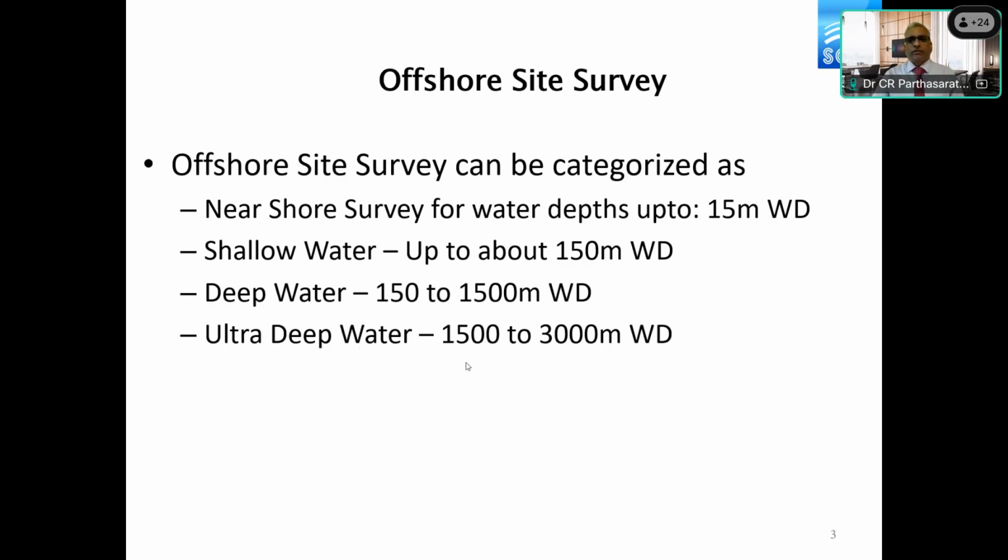The offshore site survey is the first step in the assessment of any offshore structure, to have the survey carried out and get the information. We categorize the projects into different categories. Near shore is up to 15 meters water depth. Shallow water is up to around 150 meters water depth. In the context of jack-up rigs, probably 100 to 120 meters is the limit that we currently see on the capability of jack-up rigs to operate.